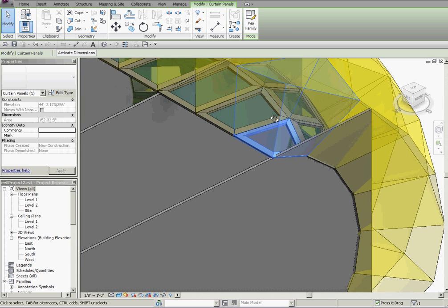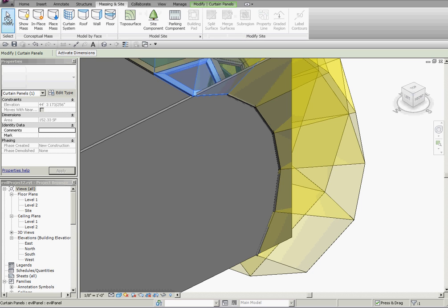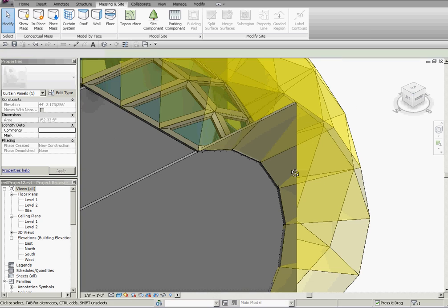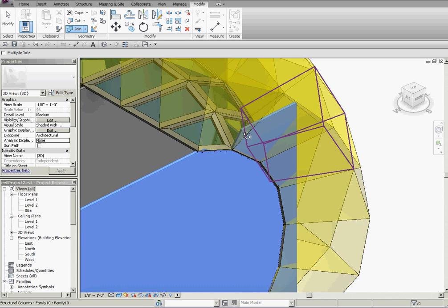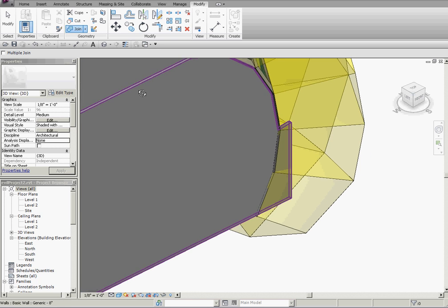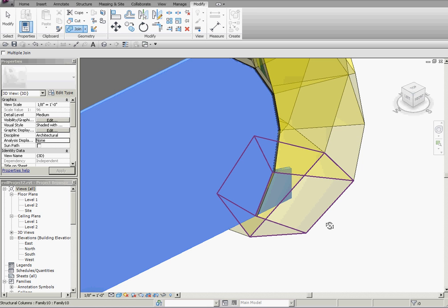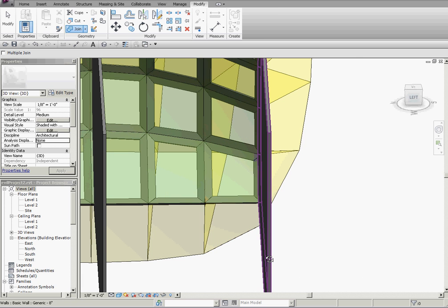And what I'm going to do now is that these ones are each a structural column. And I turned off my massing. So now what I can do is I can actually go through and go to modify, and I can join, and I can start using those structural columns to cut my wall. And the reason that structural column is nice here is because it has cut dominance. That is to say that if you've got a structural column in a wall, structural column is always going to win. So you can see, you can just walk it right through and cut off all these edges.